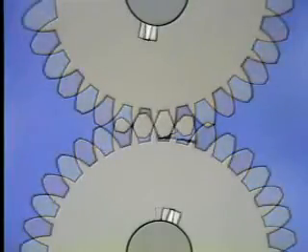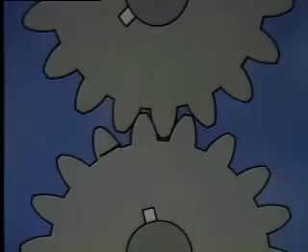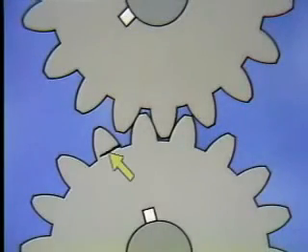As the gear tooth passes through its mesh, the tooth is loaded and then unloaded. This loading and unloading process will cause the original defect to increase in size. And eventually, the defect will grow large enough that the gear tooth will break.